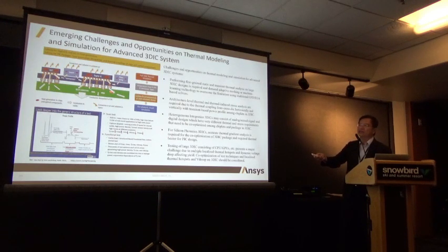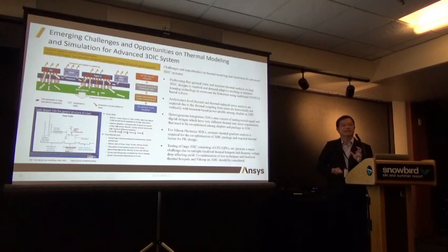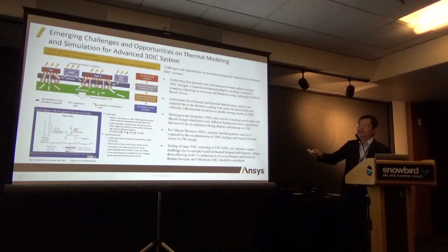For example, from the press release, NVIDIA is working with TSMC on COUPE, C-O-U-P-E, and they have more than 10 to 20 thermal sensors for the silicon photonics system. The sensitivity is plus or minus 1 degree. So it's very important to get the thermal simulation as the boundary condition for the PIC, and then you can run a very detailed numerical simulation for the waveguide and the photonics components.